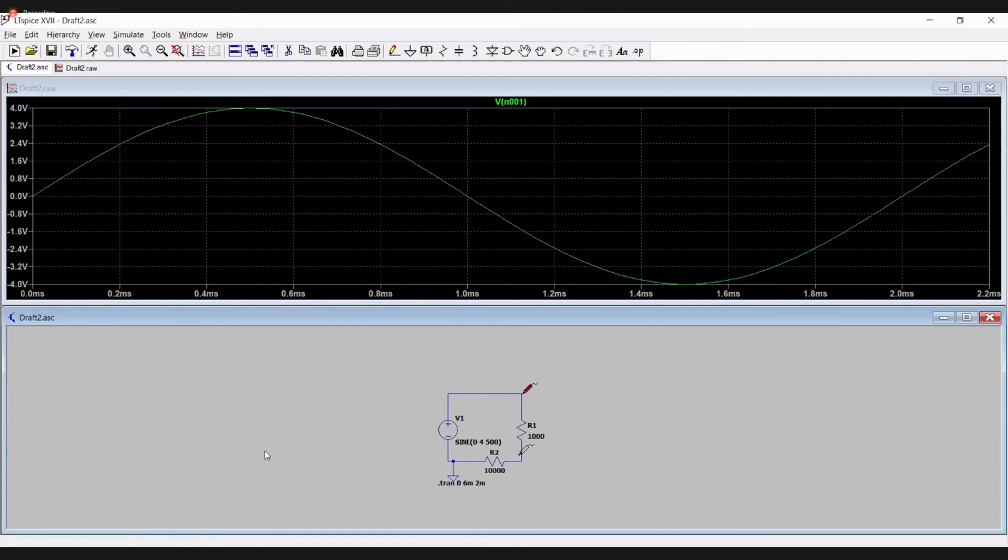You place this on the bottom node, the other side of your component, and so you would be getting the voltage drop across resistor R1. As you can see, it is small, because the voltage drop is directly proportional to your resistor. There is a much larger voltage drop in R2 because it's a much larger resistor.